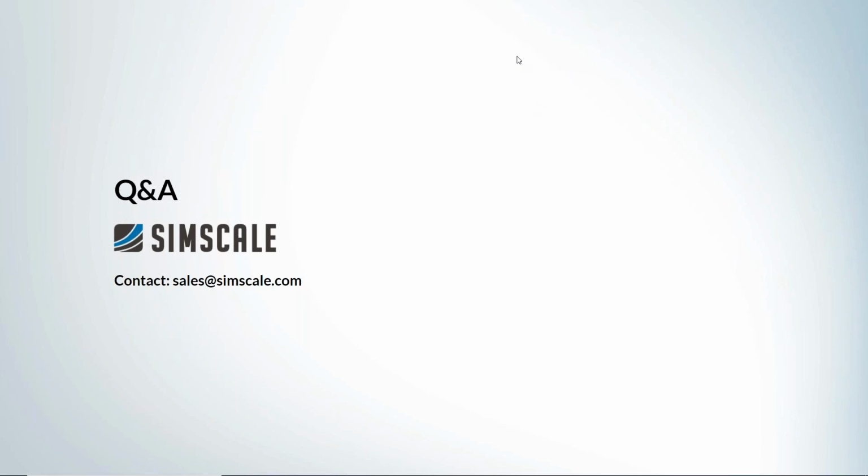Yeah, sure. You actually get quite a lot out of a standard PWC solve. We were showing the Lawson comfort criteria, which was the closest one to, say, the City of London guidelines. We also have many other variations of the Lawson criteria alongside NEN 8100 and Davenport, so quite a lot available on the SimScale platform. Additionally, we have comfort criteria based not only on the mean wind speed, but also the gust equivalent mean, which is quite useful.